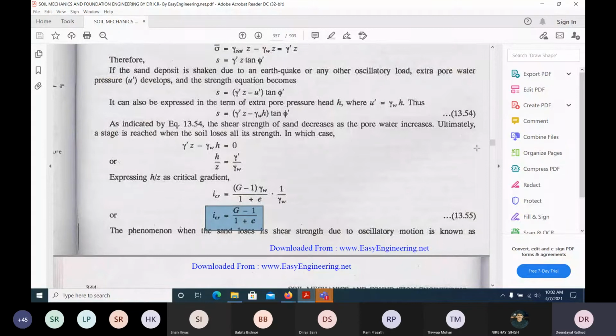This particular chapter deals with a few things you should remember. First, we took the principal stress concept. We say that in a soil there are so many stresses, but we have three principal stresses, like in strength of materials. Then we conducted a direct shear test, where the failure envelope is predefined, horizontal only.